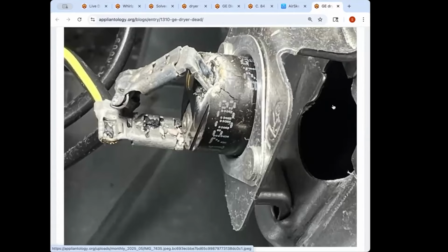Not the heat from the canister that it's feeling, but it's actually having to pass a lot of amps. Yeah, like in Tim's case, was yours gas or electric? This was electric. Okay, so you're passing some serious amps on this one. Yeah. So in Tim's case, that's absolutely what it is, 23 amps or something. It's the amps that burned this up, not the heat from the heater.